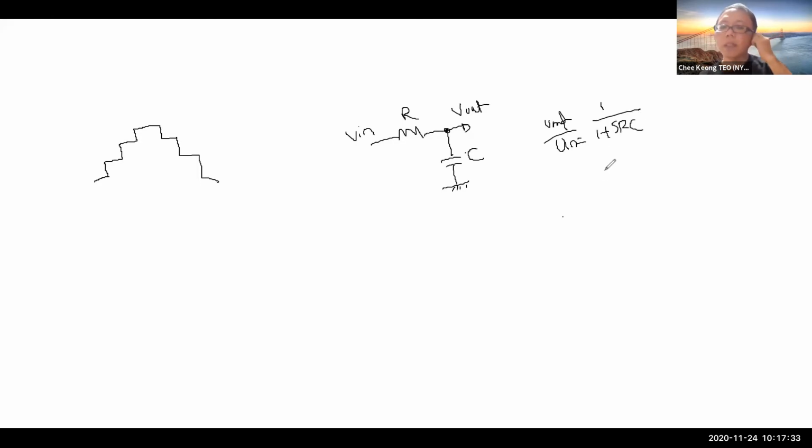So basically, essentially, you have built a low pass filter that has a characteristic that looks this way. That has a characteristic at 0 dB, and of course you have minus 3 dB, which is your cutoff frequency. This is minus 3 dB.